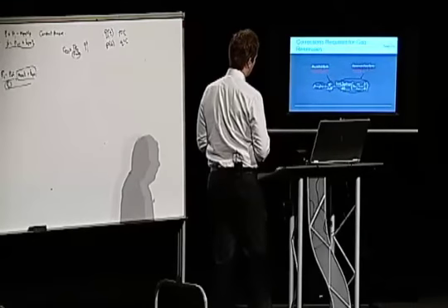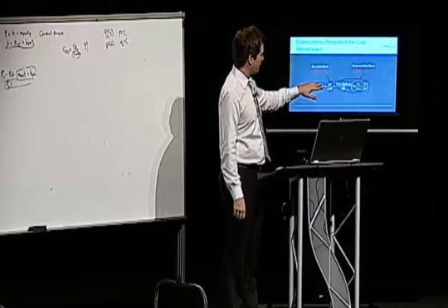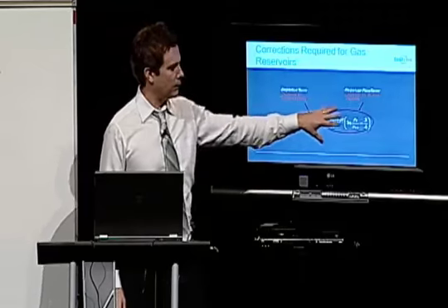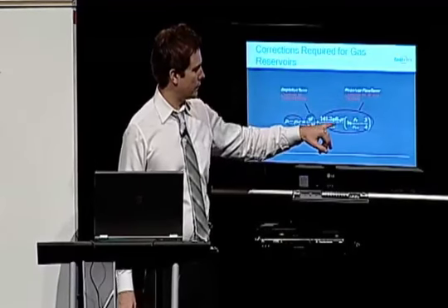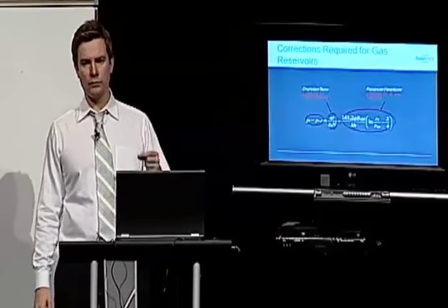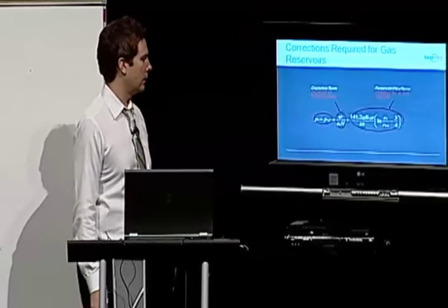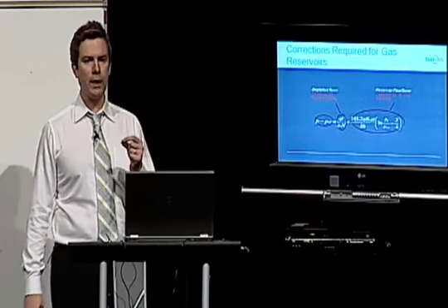So what you're looking at here is the pseudo steady state equation for oil written out in full. Okay? The term that's circled over here, this full term is the b pseudo steady state. So this is the inverse or reciprocal productivity index. And then the term up here is the depletion term. So this is where the material balance comes in. This is where the steady state inflow comes in. And gas properties are going to make an appearance in both of those terms in different ways.